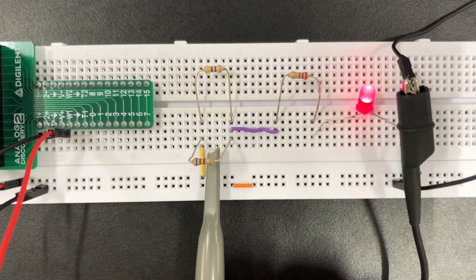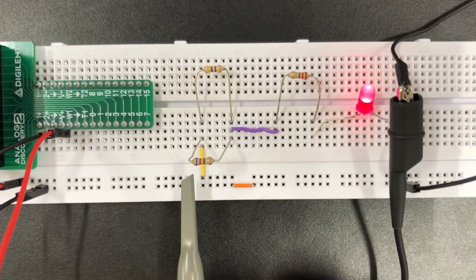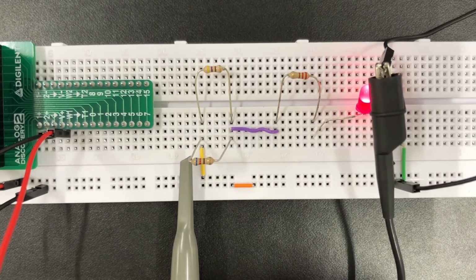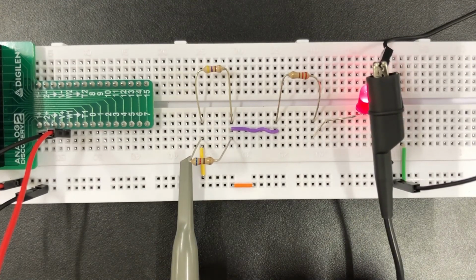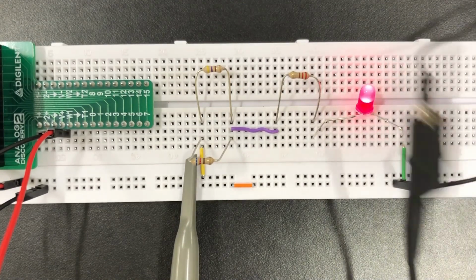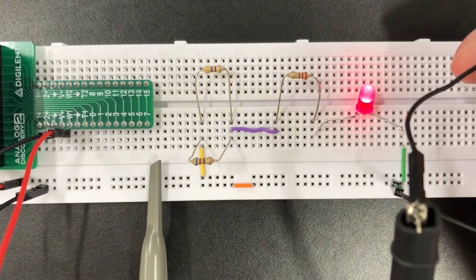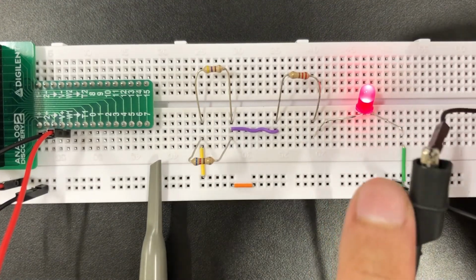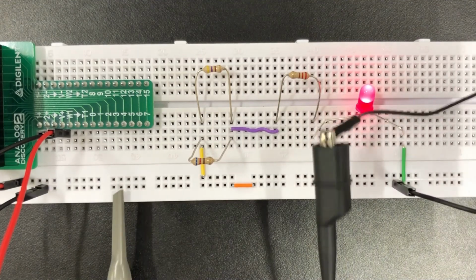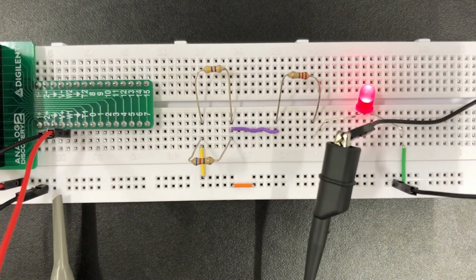And so if I do want to do multiple readings at the same time, I do need to connect my second oscilloscope probe to the second terminal, or channel 2 terminal, on the BNC adapter. And I do have to connect it to either another ground or the same ground if you can manage connecting that second alligator clip to this lead right here. So that's generally how you measure voltages using the oscilloscope probe.